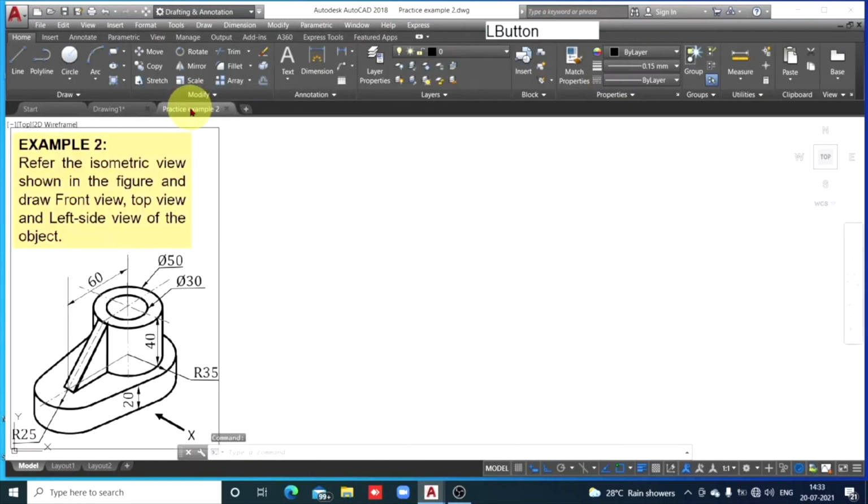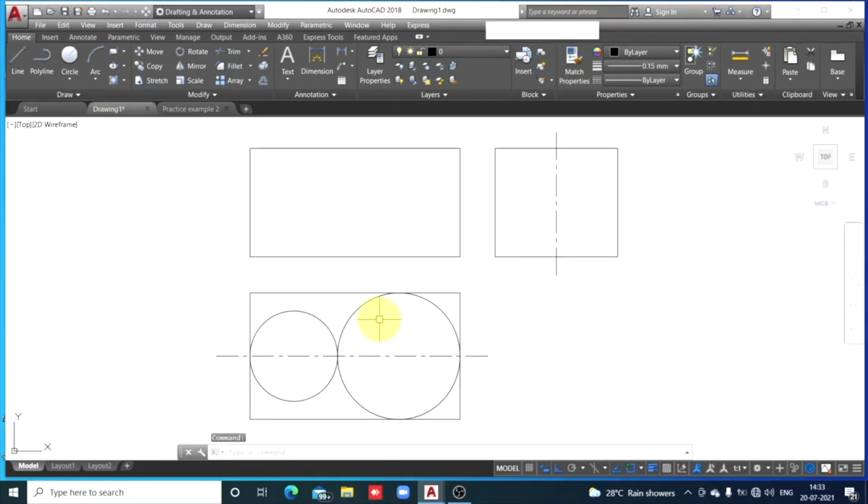Now watch it. There is a straight line here. It is not principal edge. This straight line meets the curved edge somewhere here. Also this straight line meets the bigger curved edge somewhere here. But those points of contact are not sharp corners. That means this non-principal edge is tangent to the curved edges. So we are going to draw tangent to these two curves. So how to draw those non-principal edges which are tangent to these two circles?